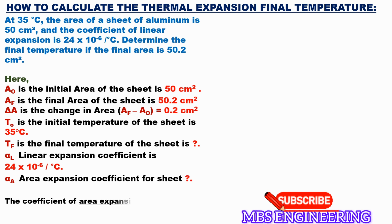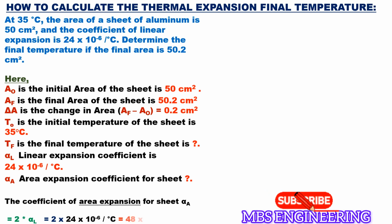The formula for calculating the coefficient of area expansion for the sheet, alpha A, is 2 multiplied by the linear expansion coefficient alpha L. Therefore, the area expansion coefficient is 2 into 24 into 10 power minus 6 per degree Celsius. Therefore, alpha A is 48 into 10 power minus 6 per degree Celsius.